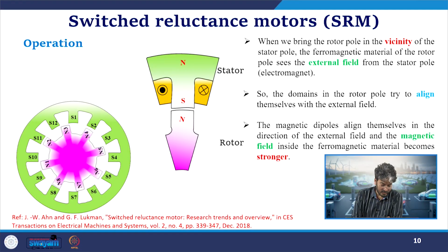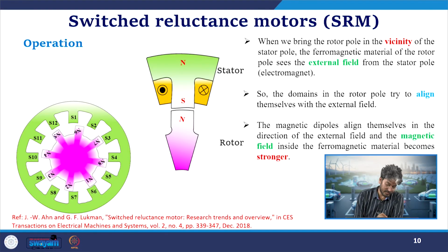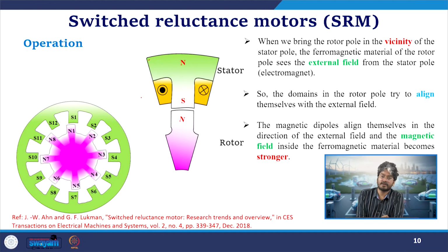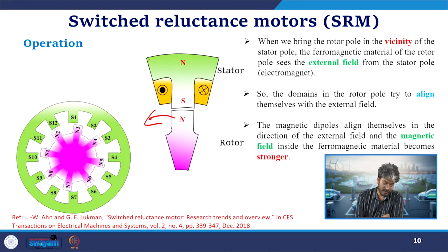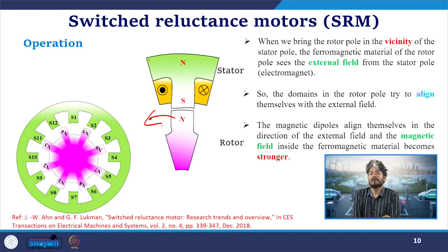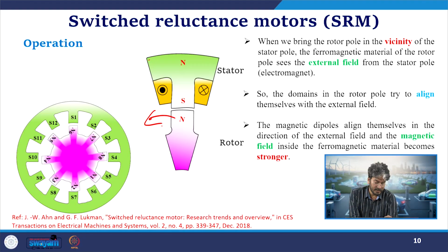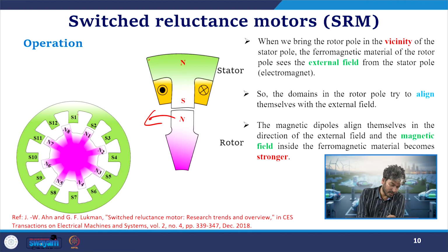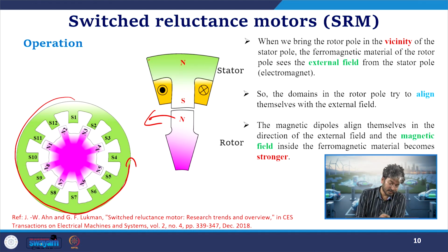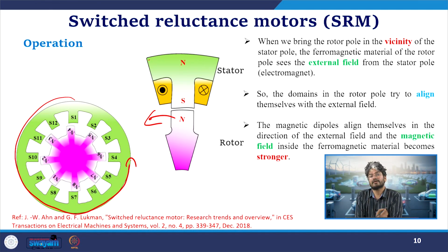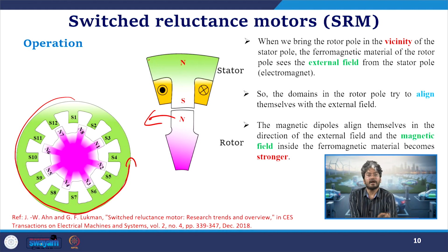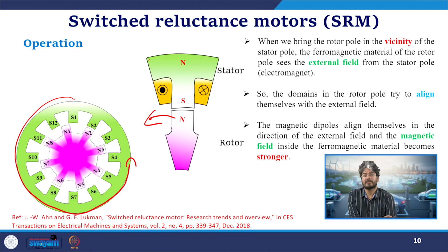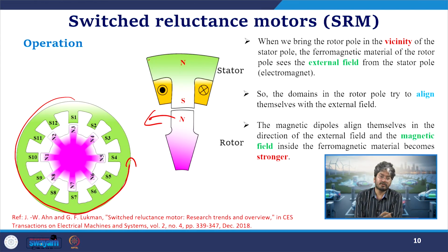Okay. So, as we continue this, suppose my rotor has been aligned, now I will go for the next phase and I will try to excite it such that again it will introduce another attraction force. When I repeat this task throughout all my stator slots, that is, cyclically I will be exciting one or more of the coil sets, and I will be removing that and exciting the next set, so that my torque will be continuously produced in one direction.